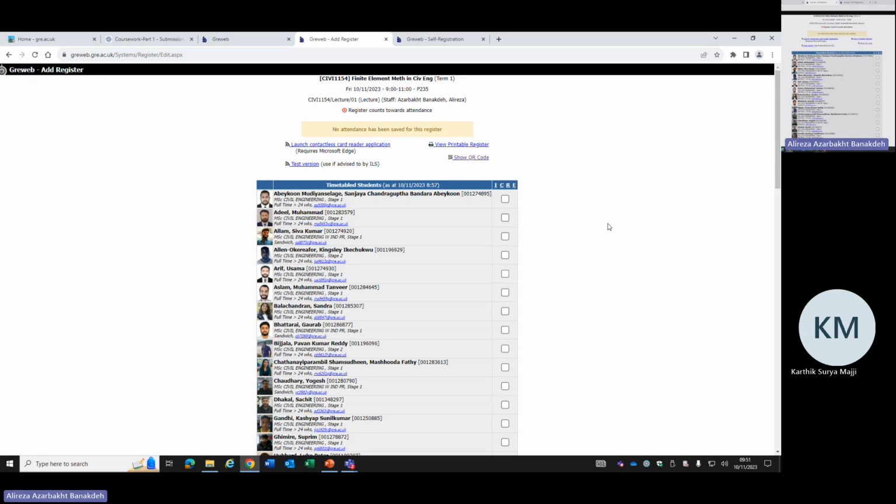Okay, with this X and Y, everything is free but translational Z, because it's out of plane, and rotational X and Y, because you can only have rotation Z. Rotation X and Y are closed.